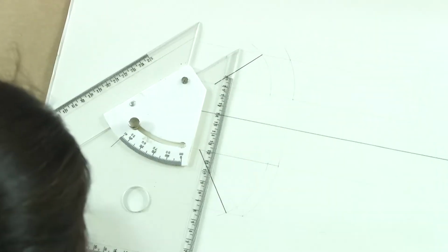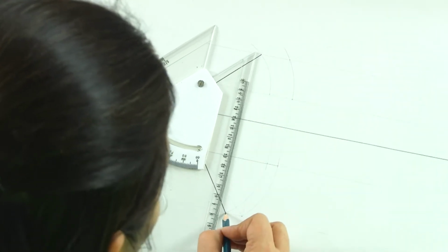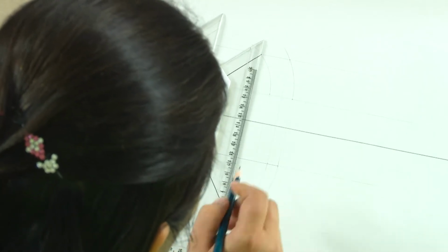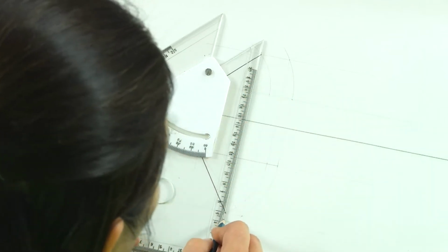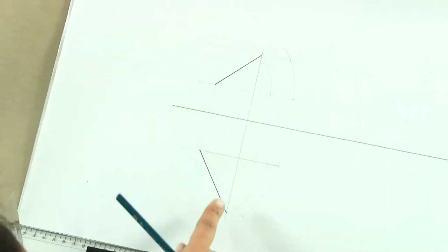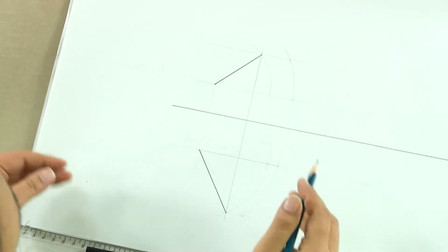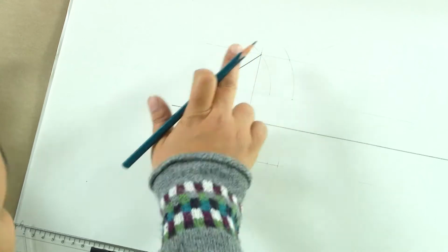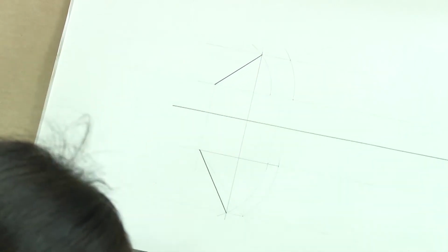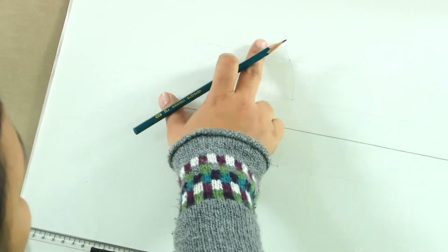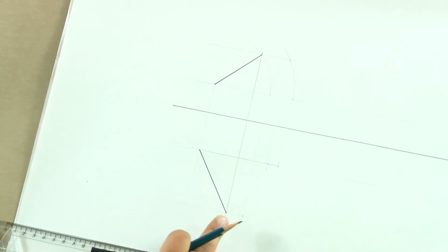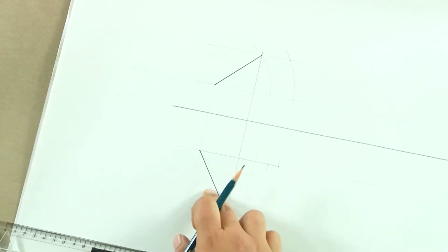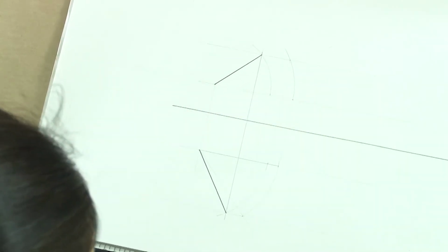So, this is the top view, this is the front view, and if you can see clearly, I will slightly darken the projections for you. This projection that we are getting here, we got it both ways. We could have done it like this, or we could have done it the reverse way. In both the cases, the projection for both these lines should have matched, and they are matching. So, that is the beauty of this graphics, and these are the projections of doubly inclined lines.